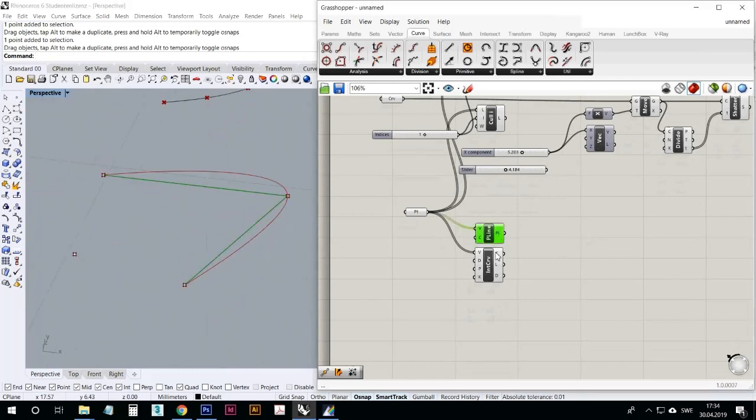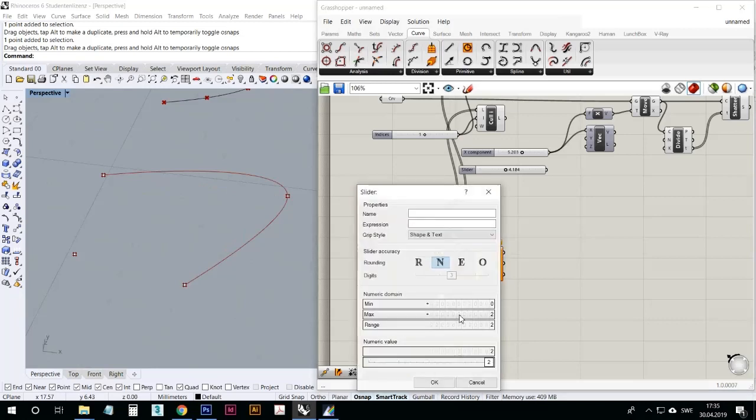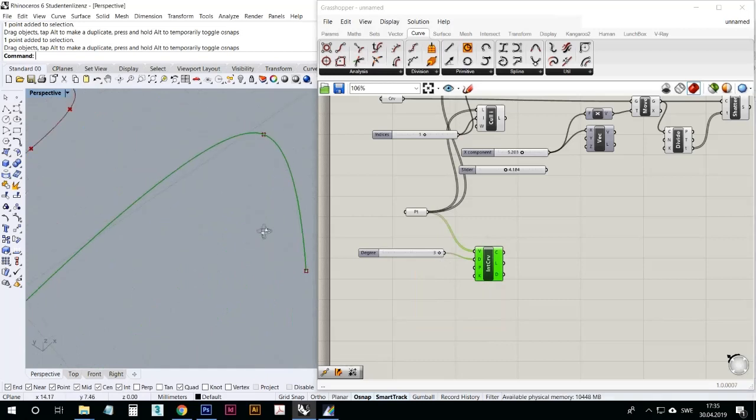That's the polyline curve. And here, if I then toggle between different degrees, like 1 degree, and I delete my polyline curve, you see I can toggle between these. Of course, this should go to 3 degrees then, because the interpolation curves only understands 1 degree and 2 degrees. So here, for example, is an interpolated curve with 1 degree. It's actually a polyline. And then you go to degree 3, and it looks like this. Then it's a control point curve in Rhino, really.